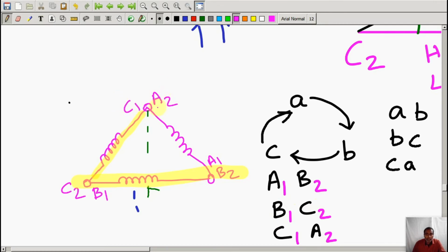So that way also you can check, or you can simply check whether start and finish are connected or not. For the delta connection, start and finish, start and finish. So you can see that the polarity of terminal C1 and A2 are not the same, they are opposite. Likewise the polarity of terminals A1 and B2 are not the same, but this is your delta connection. So for delta connection, this is the way we are connecting it.